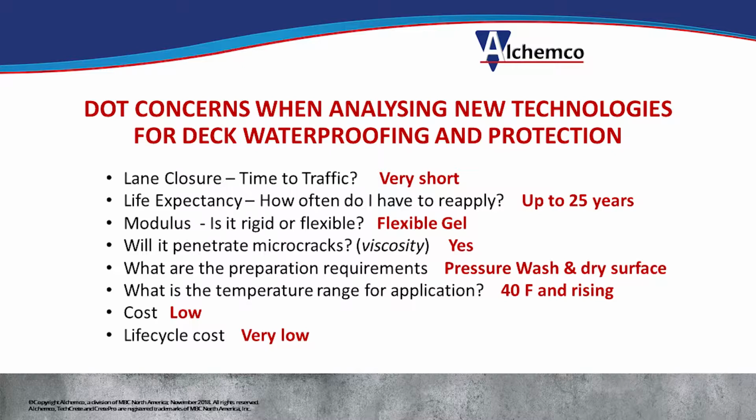The other question is whether the material penetrates micro cracks. At the end of the day, this material is as thin as water. The viscosity is very similar to water. So if water can penetrate that micro crack, this technology is also going to be able to penetrate that crack.